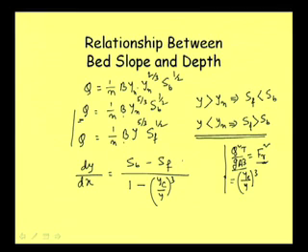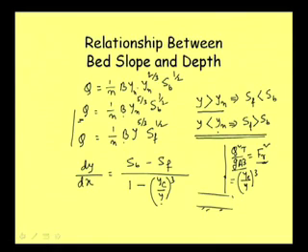Now, if our depth of flow y is greater than yn, and suppose in zone 2, say in zone 2 we can say the depth of flow will be less than yn. If it is mild slope, then this is yc and this is yn.